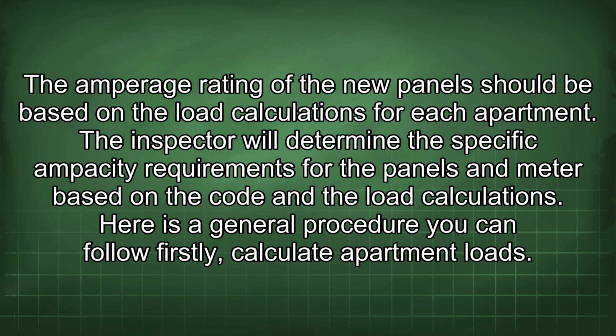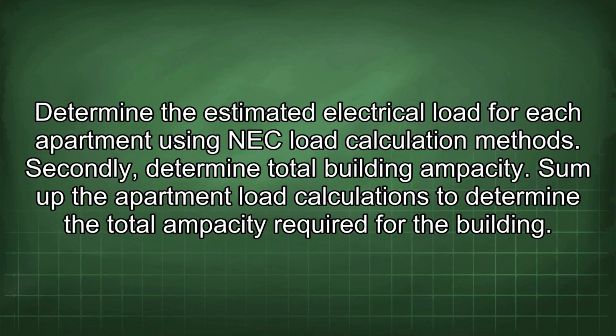Firstly, calculate apartment loads. Determine the estimated electrical load for each apartment using NEC load calculation methods. Secondly, determine total building ampacity. Sum up the apartment load calculations to determine the total ampacity required for the building.